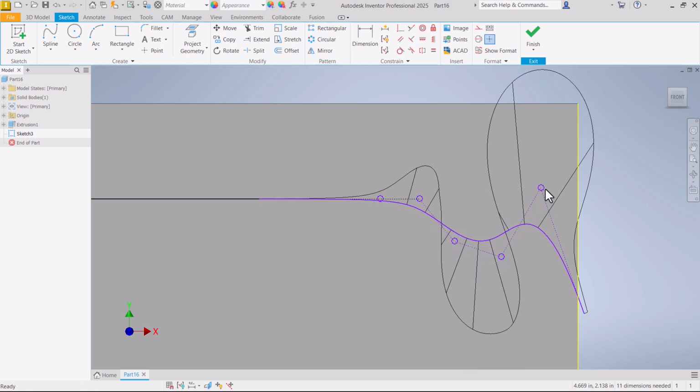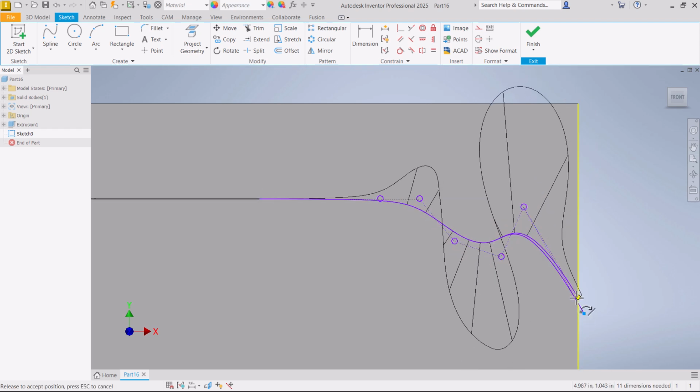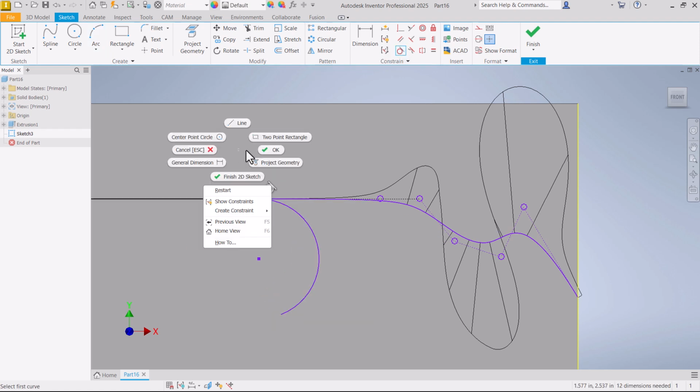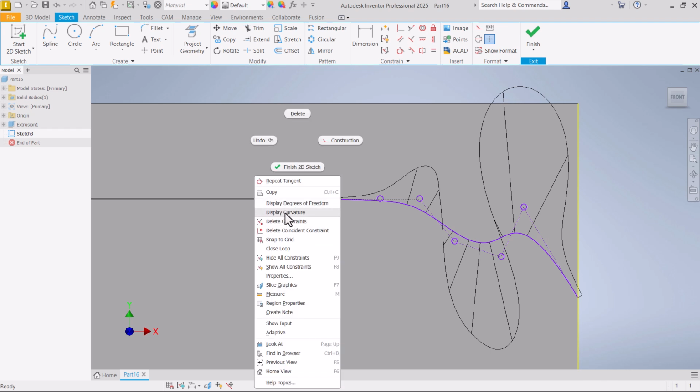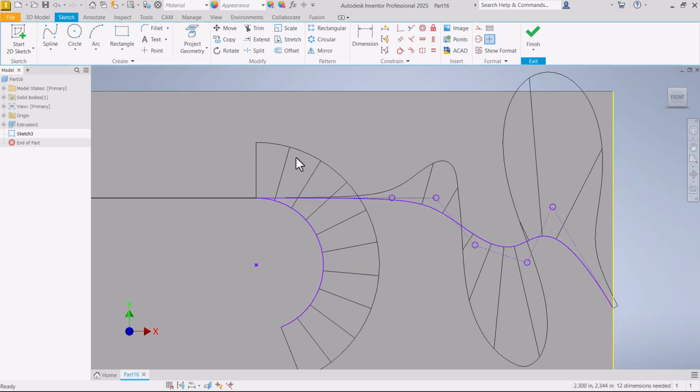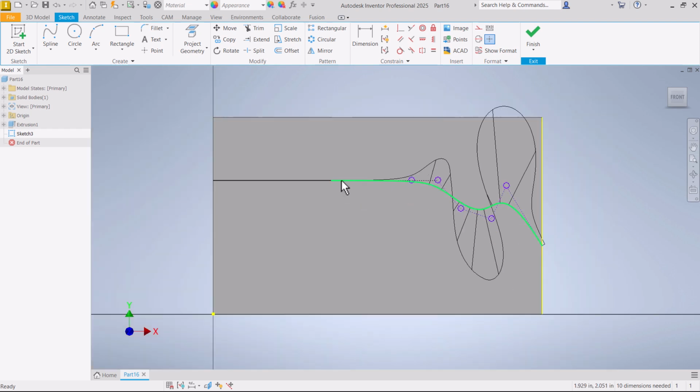That is what the smooth G2 constraint does for you. It really does smooth out this transition more so than just a tangent constraint. And I can display the curvature on that as well. See those lines that we have on that arc immediately jump into a significant amount of curvature, whereas for the spline with the G2 constraint, then we have minimal curvature there.